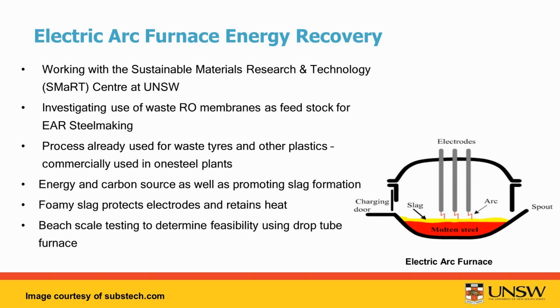Through subsequent gas release, it forms what they call a foamy slag. Now, the way that it's described to me is that it's a little bit like a cappuccino. You've got your foam sitting on top of the molten steel. As you can imagine, that helps retain some heat, increasing the efficiency of the system. It also protects the electrodes and the ceramic walls of the furnace, all in all increasing the effectiveness of the system.